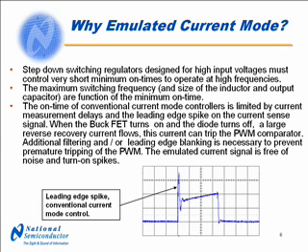The on time of conventional current mode controllers is limited by the current measurement delays and what's referred to as a leading edge spike of the current sense signal. When the buck FET or MOSFET turns on and the diode turns off, a large reverse recovery current flows. This current can trip the PWM comparator, forcing a premature turn-off of the switch. Generally, additional filtering and/or leading edge blanking is necessary to prevent this.